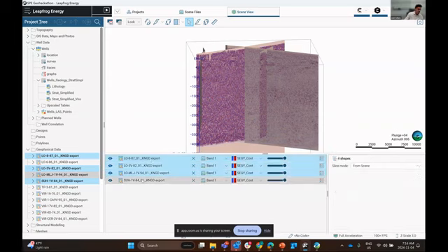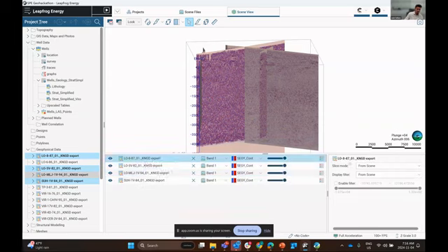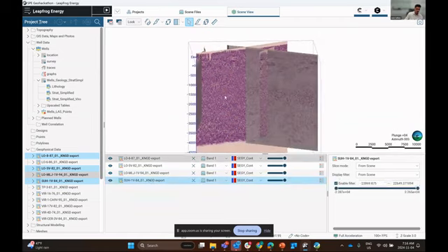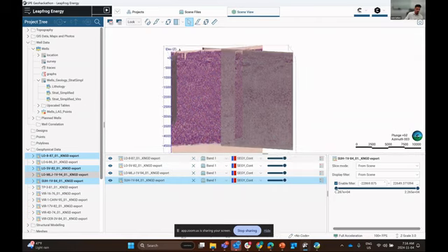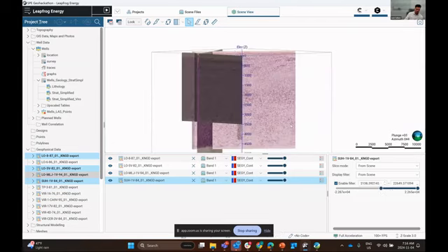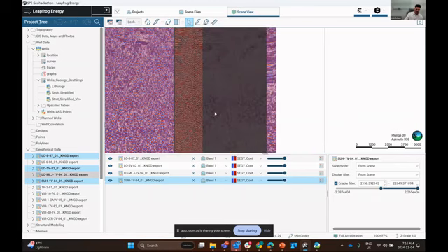Oh, sorry, this is the shape list. The properties panel is directly to the right of the shape list. So any object that you select in the shape list, which is highlighted by blue, so left click, this will open that object in the properties panel. And this is where you can run additional filters and processes to, again, optimize how these objects are visualized within this 3D scene. So, for example, this geophysical data, because it has numeric values associated with it, we can enable a filter, and we can filter information based on this slider right here. So that's this geophysical data set.